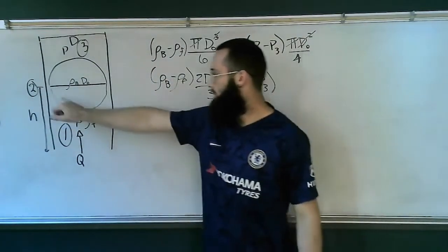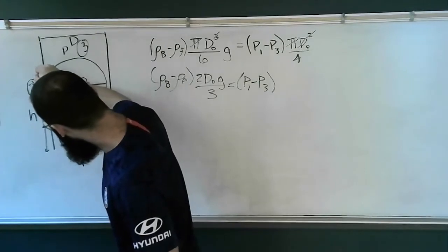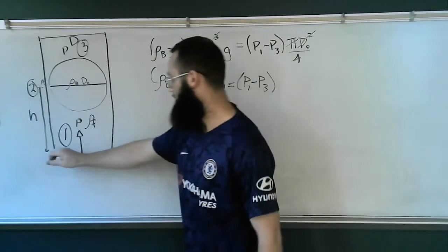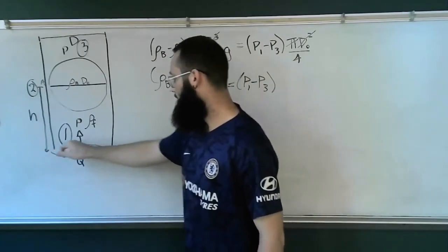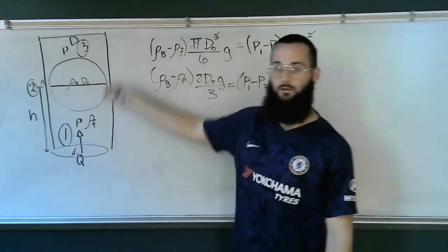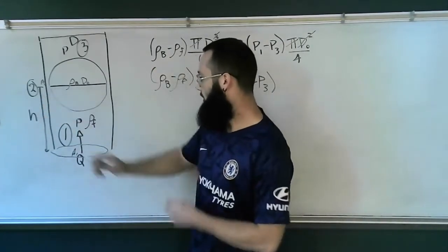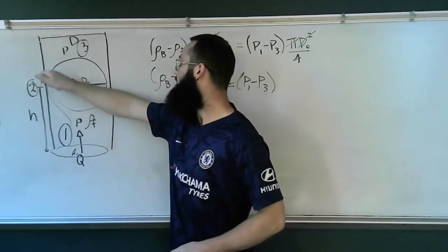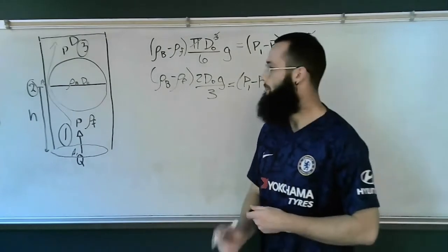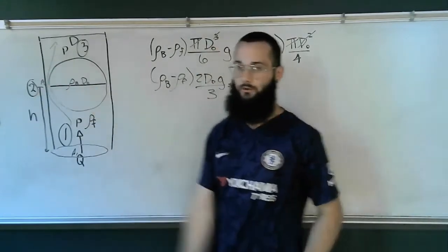If you look at this figure here, we can see that this area here, A2, is very, very small compared to the cross-sectional area of the entire column. Because of this, once this flow comes through here and then reaches out, there'll be a sudden expansion, which means we'll have no pressure recovery from P2 to P3.